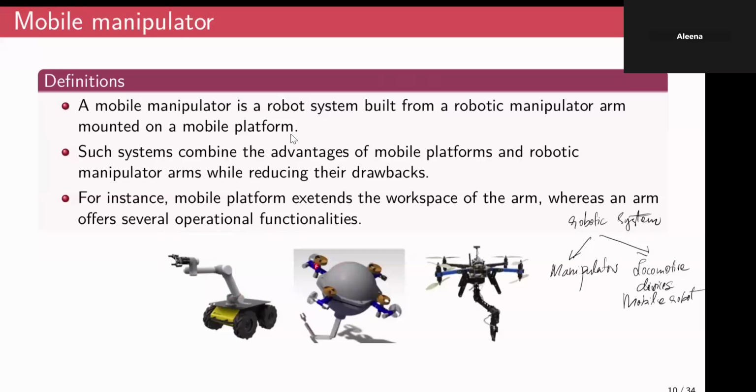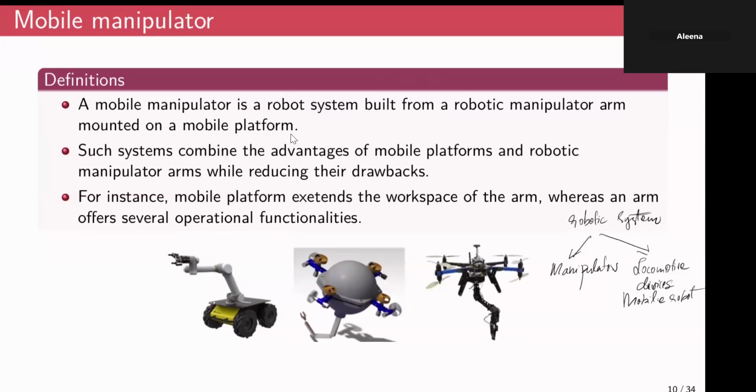Depending on how much thrust each of these thrusters makes, the robot can execute all 6 degrees of freedom. And using a very similar principle, you have the third example where a robotic manipulator is mounted on an aerial drone. In place of thrusters, you have rotors, which provide the necessary thrust for the aerial robot to move in all 6 degrees of freedom.